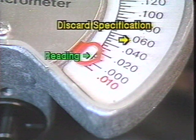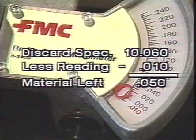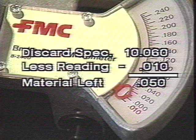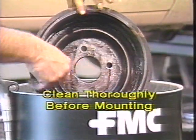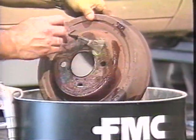If this number is greater than the discard specification, stop. Inform the customer that the drum has served its purpose and must now be replaced. Micrometer readings less than the throwaway specification need to be subtracted to determine the amount of material left in the drum. Record this amount. If full of brake fluid, clean the drum thoroughly before mounting it on a brake lathe.